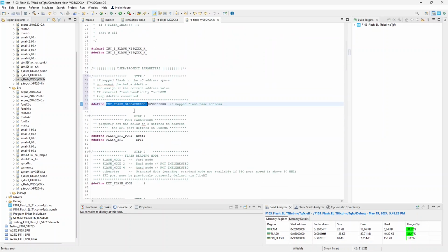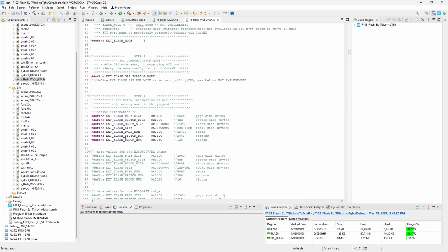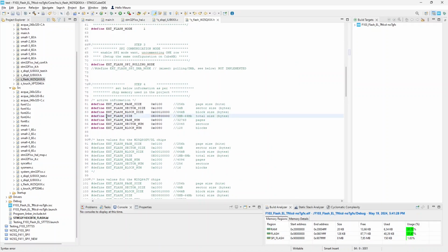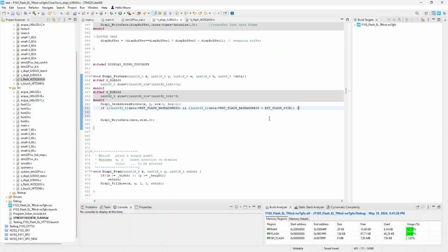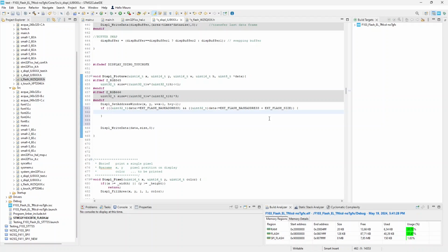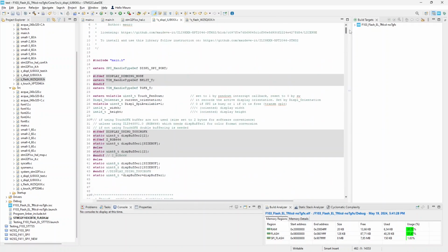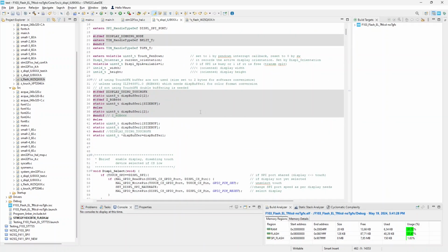Here I can refer to another available macro, indicating the flash size. If we are inside this range, data to draw is on the SPI Flash. Otherwise, I move data to transfer as before. SPI handling is easy. I just need to read data from Flash, store it into a buffer, and transfer it to the display. I know that you are here knowing that the library I made has a data buffer to smartly use DMA on SPI.